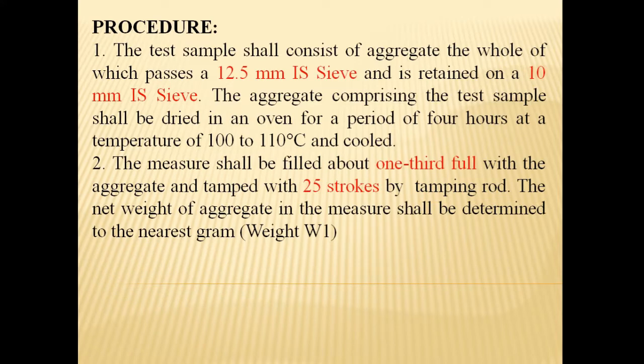The measure shall be filled about one third full with the aggregate and tamped with 25 strokes by the tamping rod. The net weight of aggregate in the measure shall be determined to the nearest gram as weight W1.